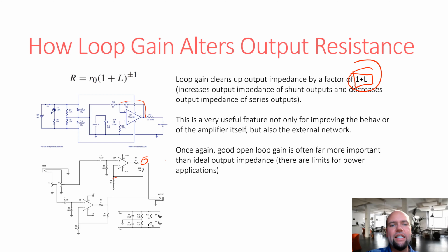So basically, this design will clean up that output. The output resistance doesn't really matter. It's going to mostly get cleaned up by the feedback, but you're going to increase your chances of clipping. So once you do go over current, it's going to start clipping that output. This approach here doesn't do that. This approach here, the only valid signal is right here. So basically this output is going to be the correct, amplified value.